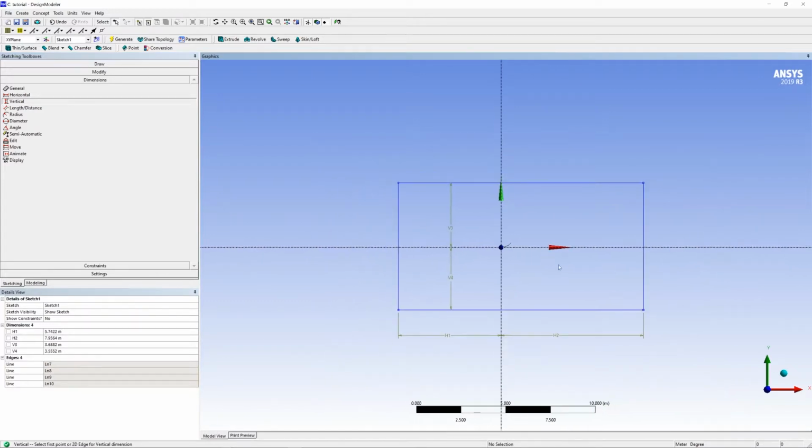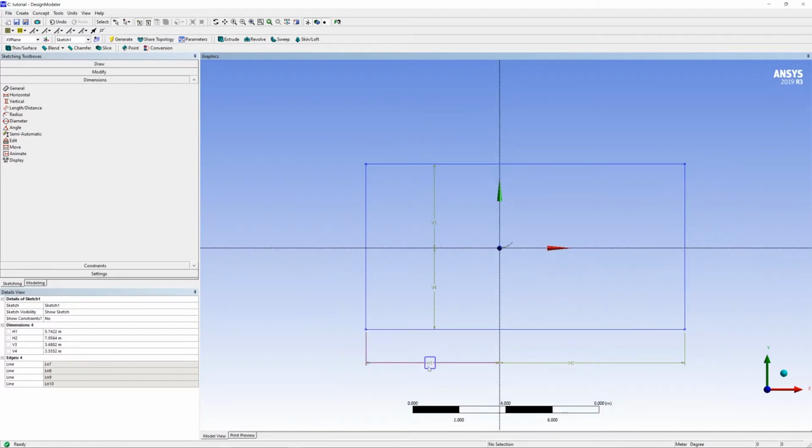And finally, we're going to dimension the domain. So if we take the approximate length of our body, or the overall chord, it's going to be about 0.75 meters, as that's the bounding box we're allowed in the rules, right? So I'm just going to approximate that to 1 meter, and I want at least 8 multiples ahead and 10 behind.